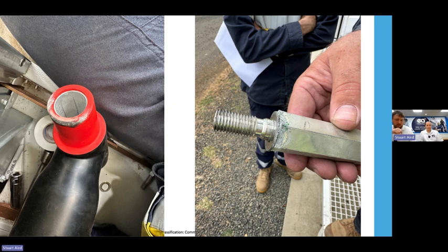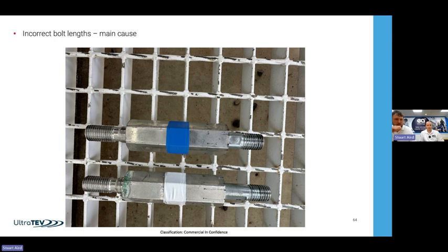Root cause for this, dead simple. Bolts are different sizes, different lengths. One phase was tight and had a slightly shorter bolt than the other two. The other two were sticking out a bit too far. So from day one, a build error, the wrong component being used, and you've now got something that would have led to failure had it not been detected. So there's a case study of how the techniques and the analysis are starting to give you confidence in these decisions. And being blunt, that's what we're there for.